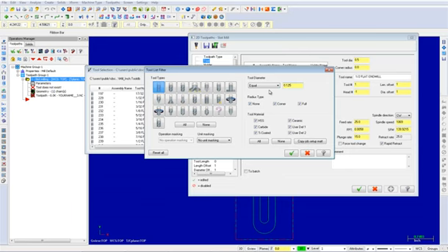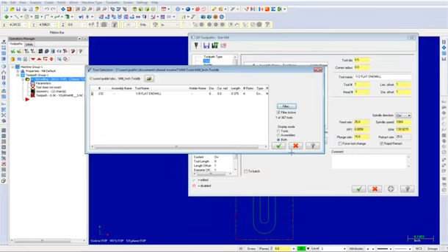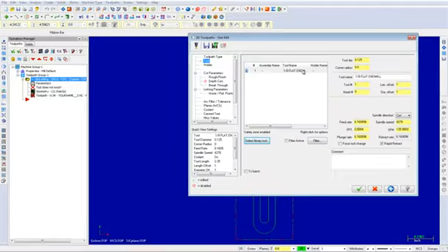Once complete, select the OK button to exit the tool list filter. In the tool selection dialog box, you should now only see a 1/8 flat end mill. Select the 1/8 flat end mill in the tool selection page and then choose the OK button. Your tool will appear as shown.